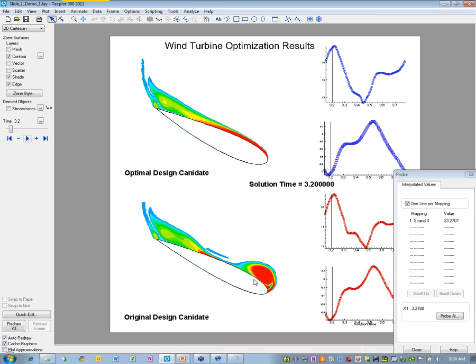So what we're looking at, you can see here we have that vortex shedding right off that leading edge. Now, as you can see, because the number of contour levels in this area aren't all that fine, it may be difficult to understand what's going on. One of the things that people often want to do is to evaluate the fine structure by adding in additional contour levels to really try to understand more about what the shape of that shedding looks like. And we can add those interactively. Again, that just gives us an opportunity to identify that fine structure.